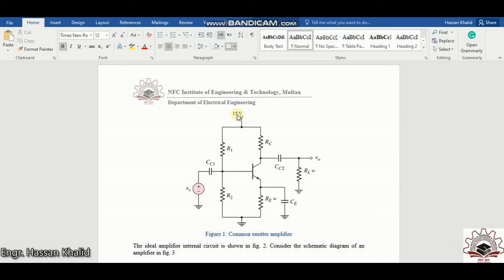Now if I'm giving a voltage that is going to exceed the limit of this biasing circuit, it will enter the saturation point. That means if your output voltage crosses the limit of that biasing value, it will enter the saturation region. In the saturation region your signal gets lost, nothing is being transmitted. So what you need to do is extend the limit of this biasing, and most probably your signal will be transmitted to the output according to your calculation.